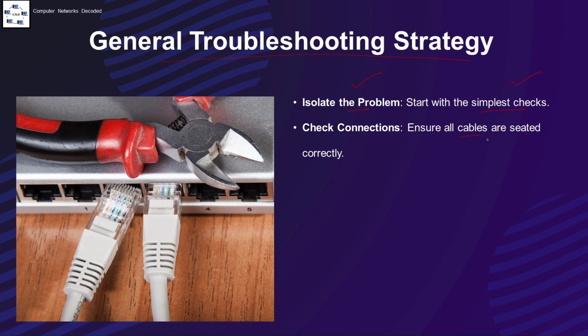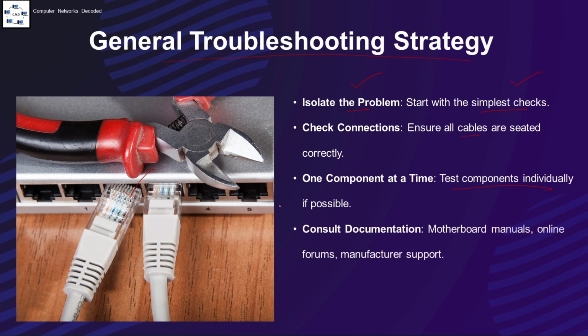You need to make sure that the cables and connectors are properly connected and seated, and you need to check one component and one issue at a time. And if you don't understand the issue, you need to consult the documentation such as the motherboard manual, online forums, or the manufacturer support.